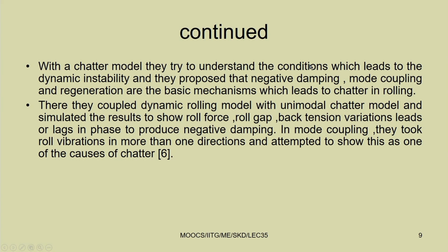They used a coupled dynamic rolling model with a unimodal chatter model and simulated the results to show that roll force, roll gap and back tension variation lead or lag in phase to produce negative damping. In mode coupling, they took roll vibration in more than one direction and attempted to show this as one of the causes of chatter.